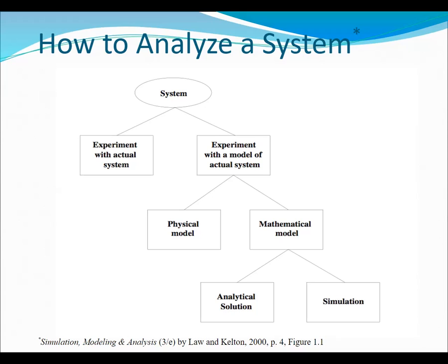They have the Webster model for intersection delay. There you're not actually measuring the delay, you're estimating it using an analytical approach. Sometimes they work just fine, but sometimes a simulation approach is better because there might be elements of the system for which you might not have an analytical solution. So that is the decision tree of how you can potentially analyze the system.